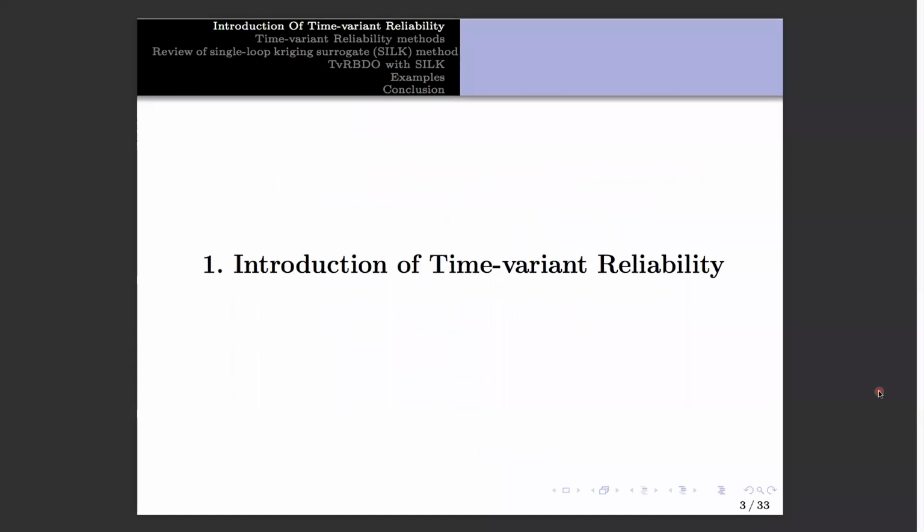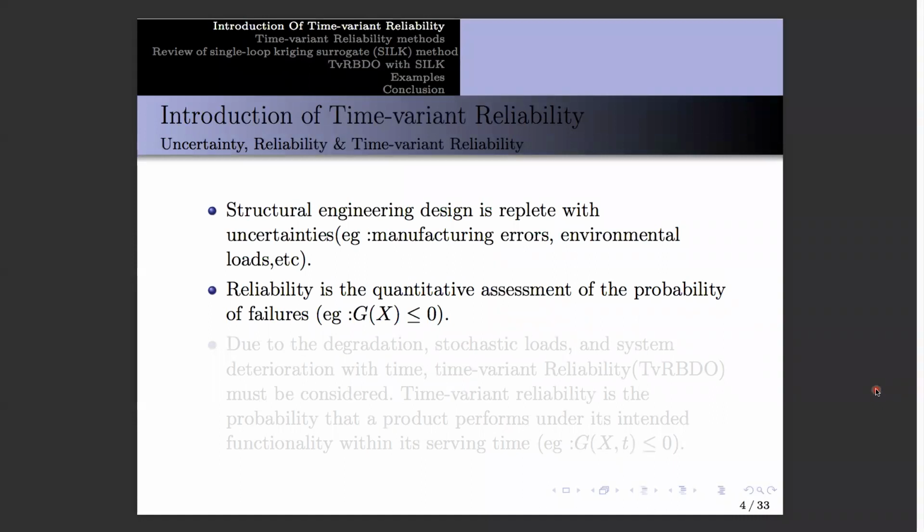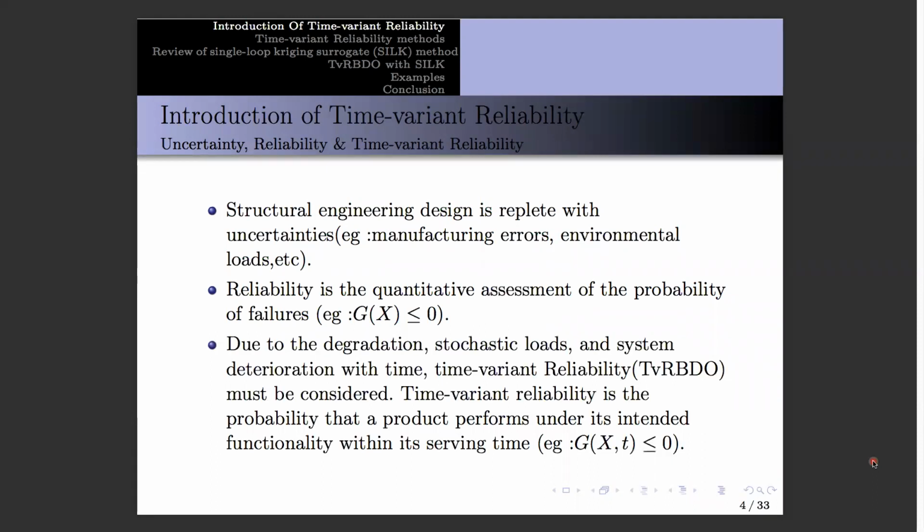First of all, what is time-variant reliability? It is an analysis that allows capturing the time dependence of the probability of failure and the uncertainty of the deterioration process. The assessment of time-variant reliability of existing substructures subjected to degradation is an important task for taking decisions on inspection, maintenance, and repair actions.